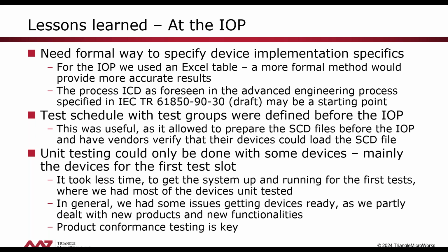One of the lessons learned: as I mentioned before, we asked the device vendors to fill in certain information in a spreadsheet. In the future, I think we should use a formal way to specify device implementation specifics. The process ICD, as it is foreseen in the advanced engineering process based on the 90-30, would be a good starting point for that. The fact that we defined the test groups and the test schedule beforehand was also useful, as it allowed us to prepare the SCD files before the IOP and have vendors verify that their devices could load the SCD files.